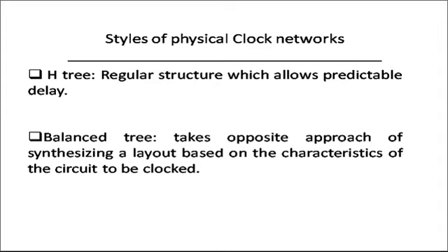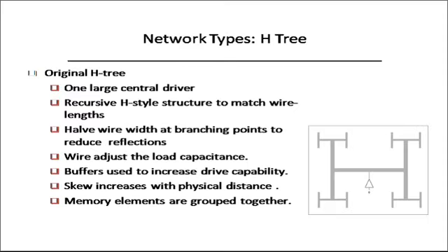You may say a grouping of certain elements, like that a balance tree is over there, and H tree is going to give you the regular structure. An H-shaped structure is over there. Now you can see from the figure also, you are going to apply the clock at the middle of the H, and whatever the flip-flops are being arranged, these are arranged at the edge of the H. Here you can read one large central clock driver, quite obvious.